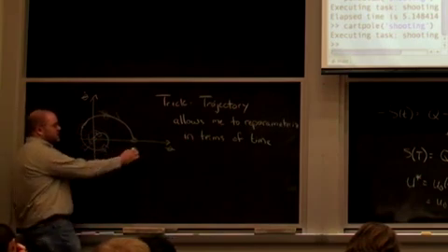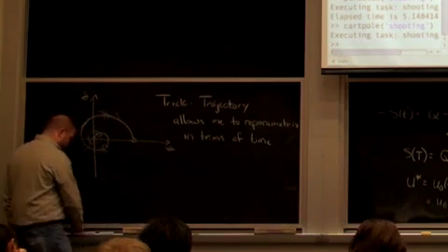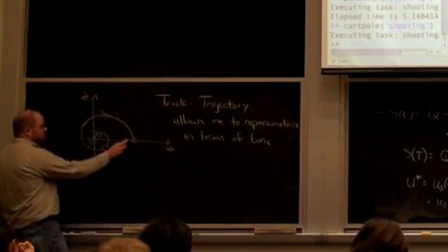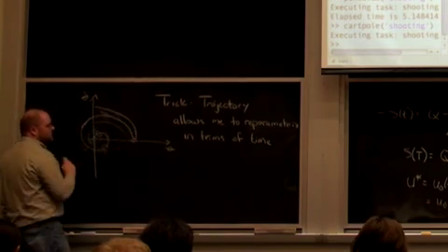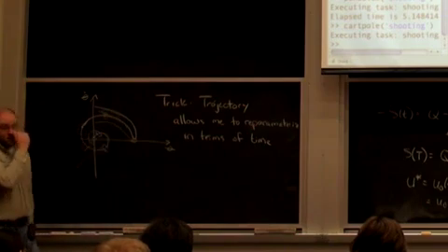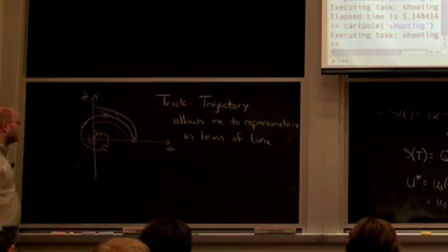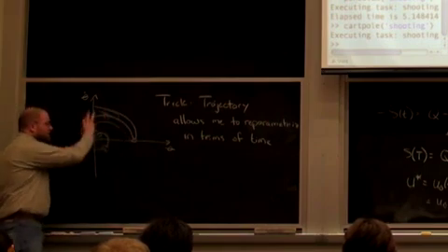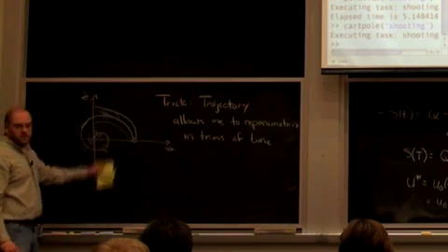So Mark knows about these tricks for computing basins of attraction pretty efficiently. These days what we do is we actually try to compute the funnel, the sort of basin of attraction of this trajectory, around the trajectory, and you could know discretely if you left that basin of attraction, right? So I'll give you the recipe for that, but it actually makes more sense, I think, in the motion planning context, where we actually will design trajectories that fill the space with these basins. This is very, very similar to the concept of flow tubes.